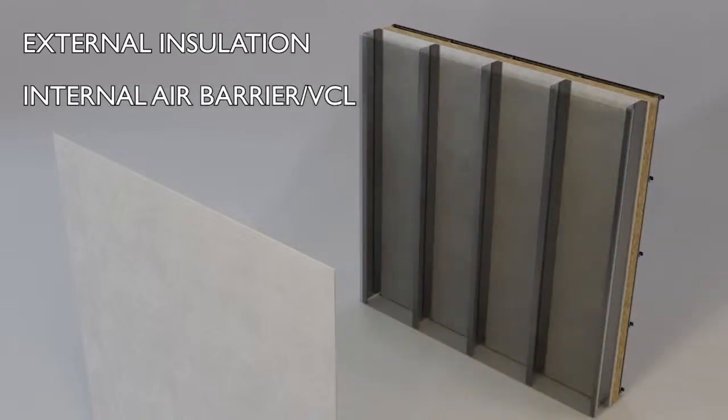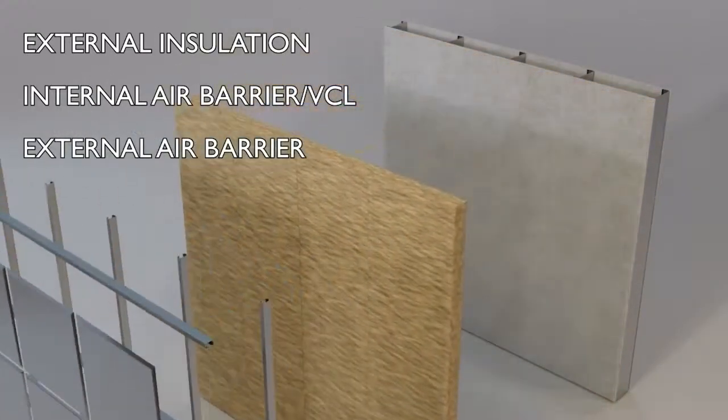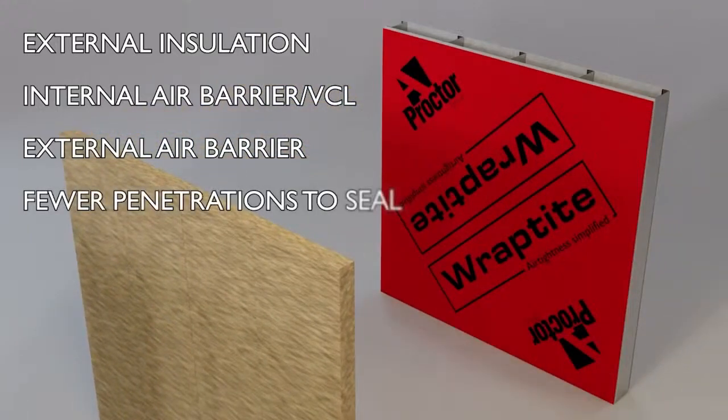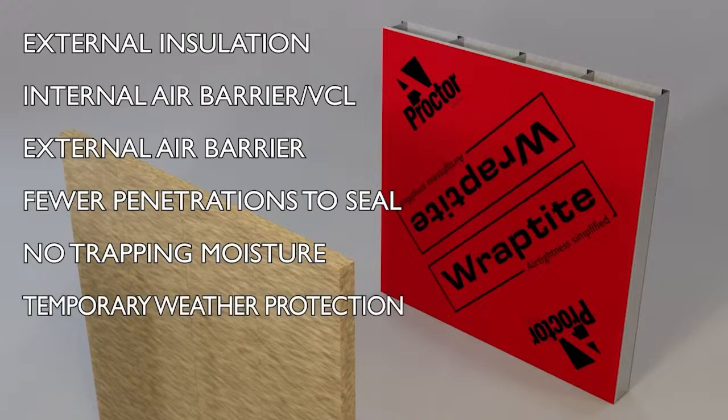Historically, the airtight line in such constructions would be provided by an internal vapour control layer, if at all. Now, however, the Airtight used externally over the sheathing provides an alternative. Placed outside the structure, there are fewer penetrations through the air barrier, and the vapour-permeable Airtight permits the escape of moisture. The membrane can also provide robust weather protection during construction, as being self-adhered to a rigid subbase, it is less likely to blow around and tear than a mechanically fixed alternative.